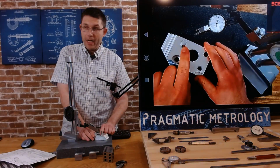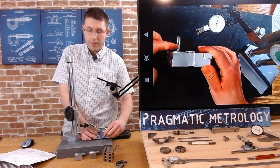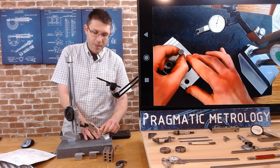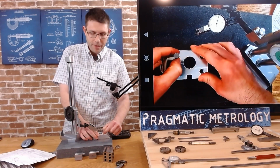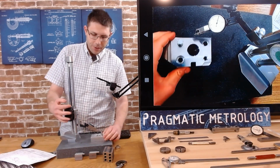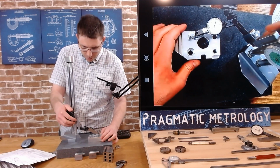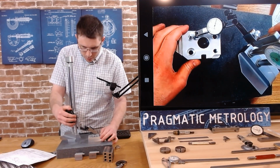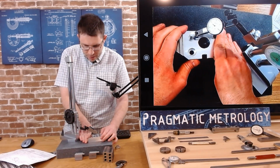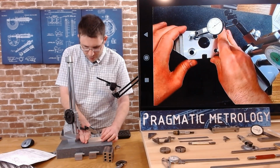We're going to measure how straight this pin is relative to my part resting on datum A and my pin registered in the hole is the largest pin. So whatever angle this hole is at, the pin is going to tell me. So I'm going to add that to my error. So I'm going to push my part into the pin and apply a little bit of pressure.